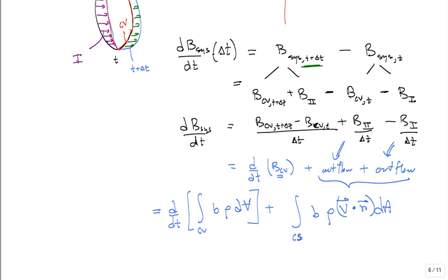So what we have is an equation that says the rate of change of the property of the system with respect to time can be viewed as how it changes in a fixed region of space and how it's being swept out, as well as that integral over the whole thing, with a negative on the inflow. That's the RTT. Oh, I forgot. What does the abbreviation RTT stand for? Reynolds transport theorem.